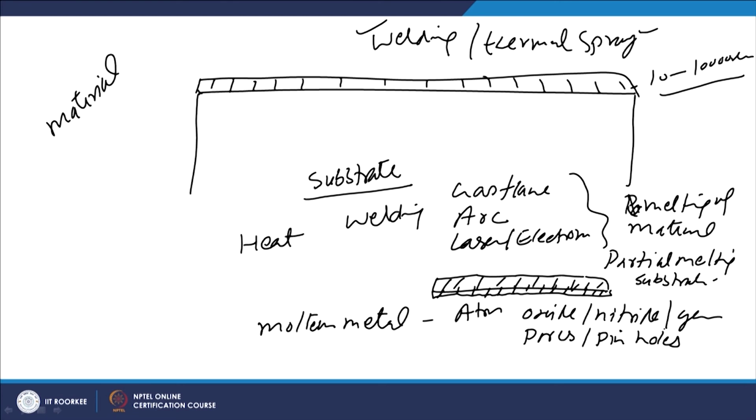This is one aspect related to the application of heat in the welding based method, where the heat applied melts, and the molten material reacts with the atmospheric gases. To avoid these interactions, we need proper protection, so that the formation of oxides, nitrides, as well as pores and inclusions can be reduced.